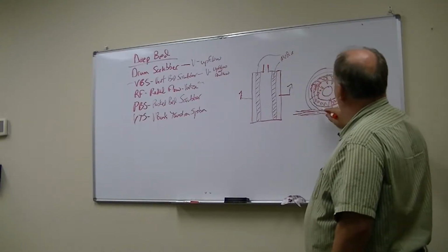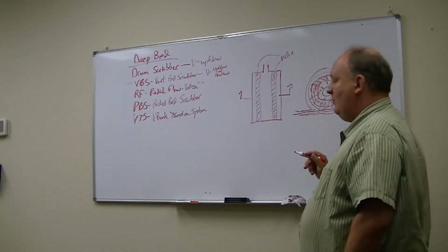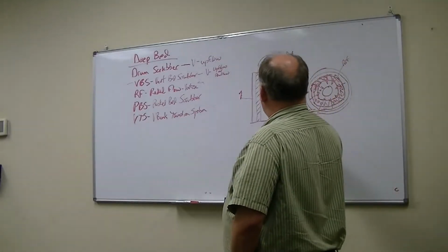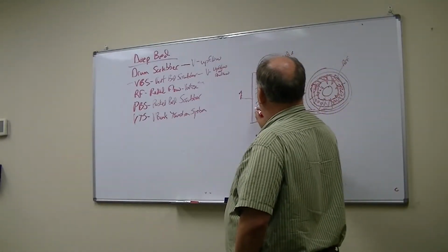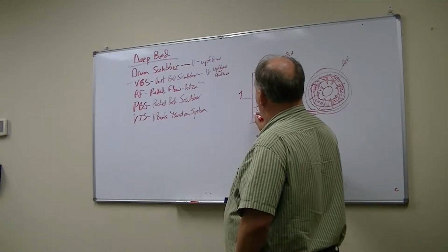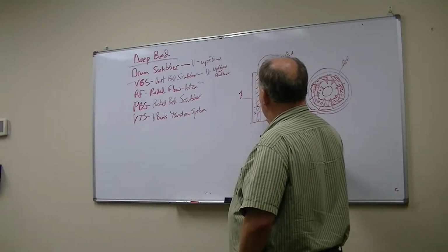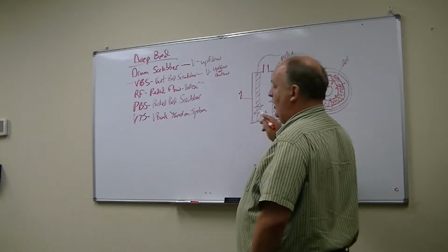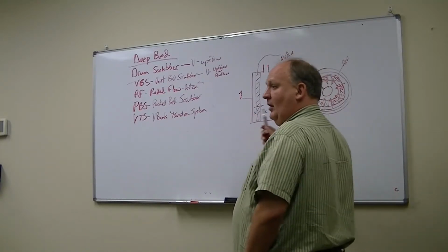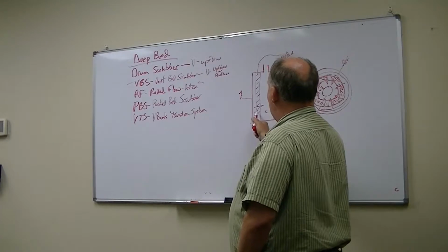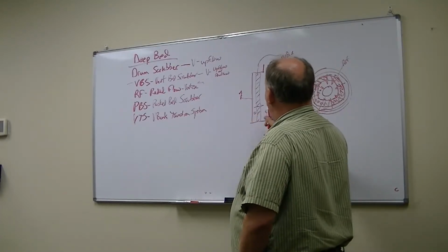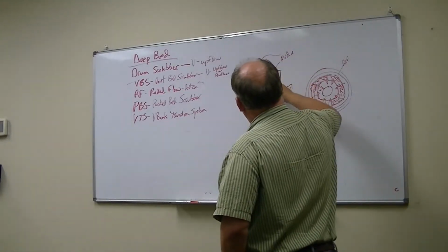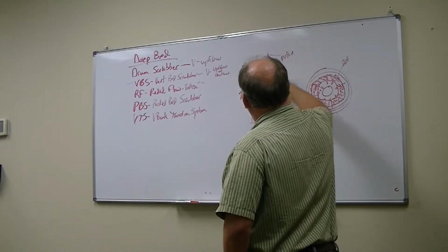Hopefully evenly, as illustrated here, okay? So this is the odorous air, and this inside is the clean air. So the odorous air is swirling around this outside plenum area, we say. It's percolating through the carbon bed, and then it goes out through the center here.